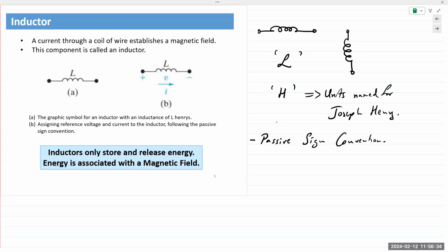When it is a capacitor, we talk in terms of voltage as application of input. For an inductor, we talk in terms of current. So when current is applied to an inductor, it goes from 0 to, let's just say, 1 amp. It cannot change instantaneously.